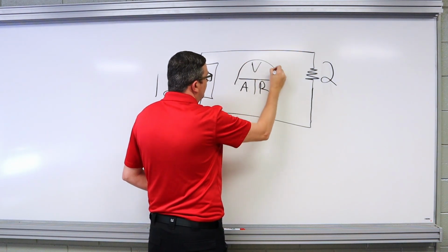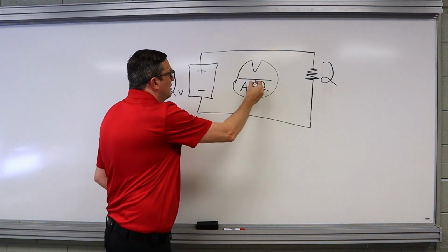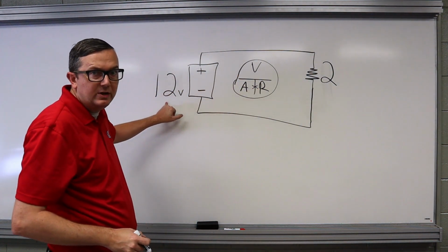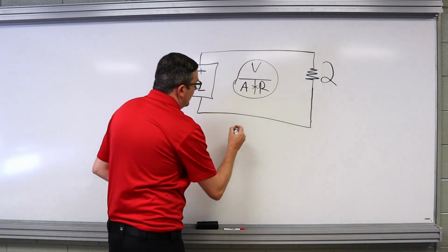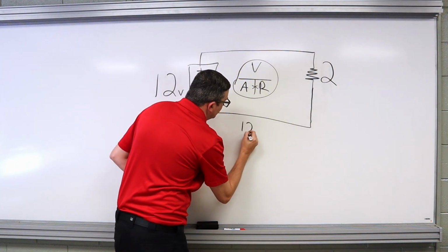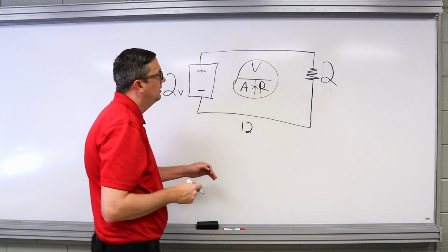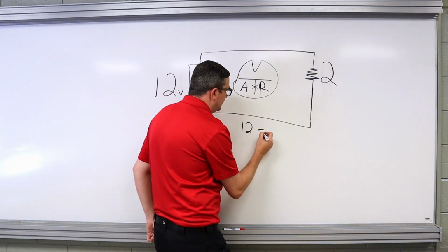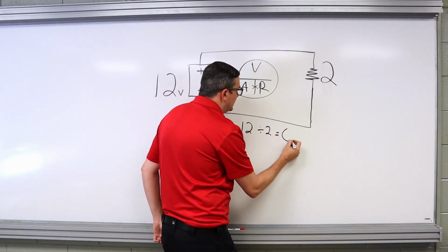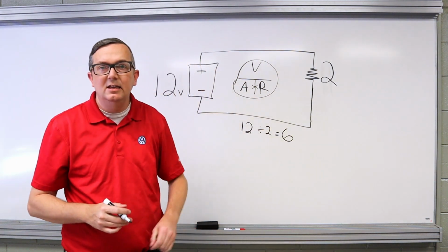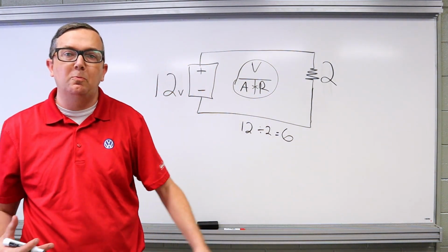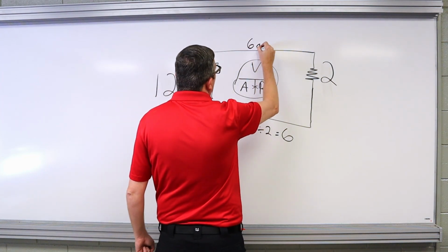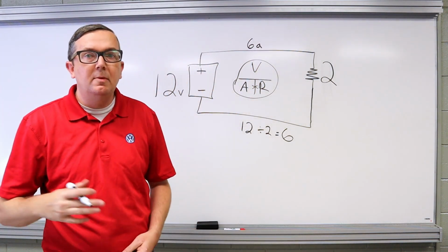my circle again. Let's draw it here. We're taking voltage, which is 12. We know voltage. And we're dividing it by our resistance, which is 2, which is going to equal 6. So 6 is how many amps we're pushing in this simple circuit. So 6 amps.